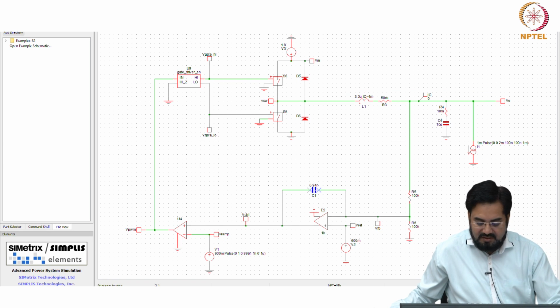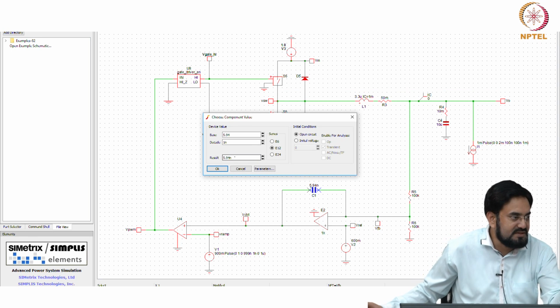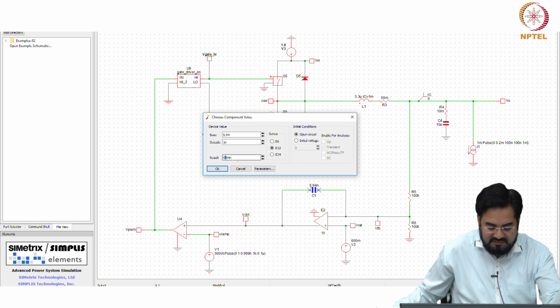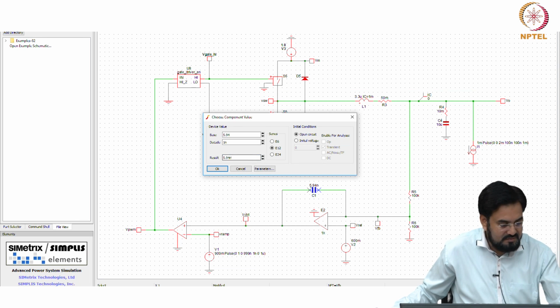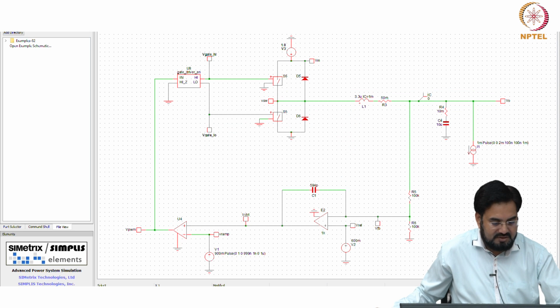Now let us say I do not include that 10 factor, means 0 dB gain margin. Then what should be the value of this? One over 10 times, correct? So it should be unstable with this, so we can check.